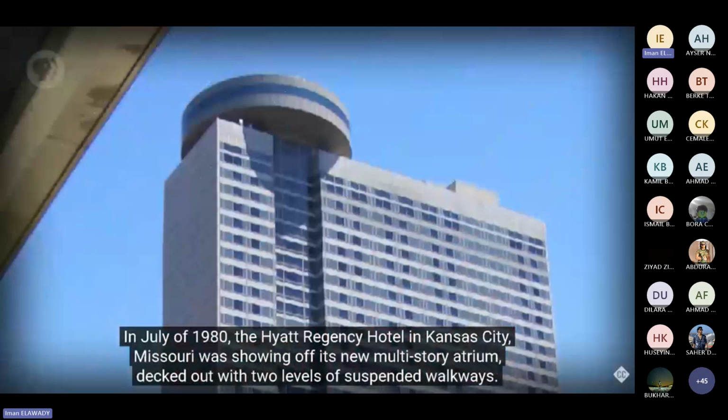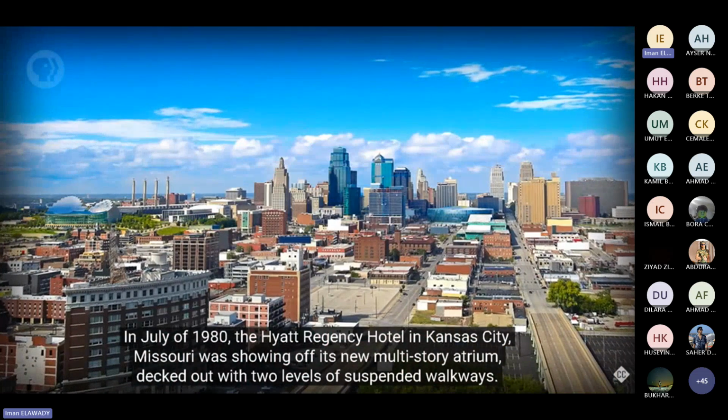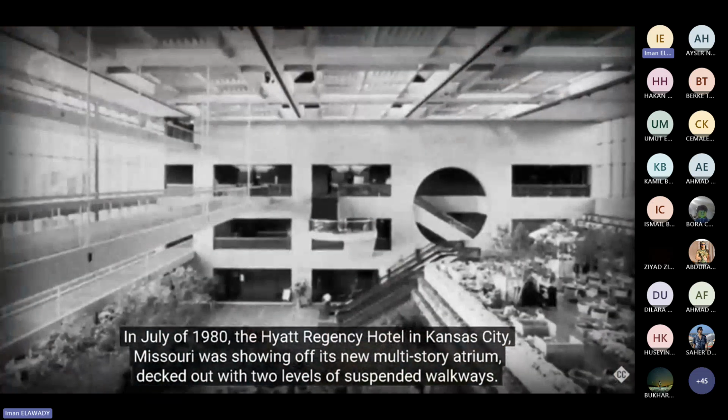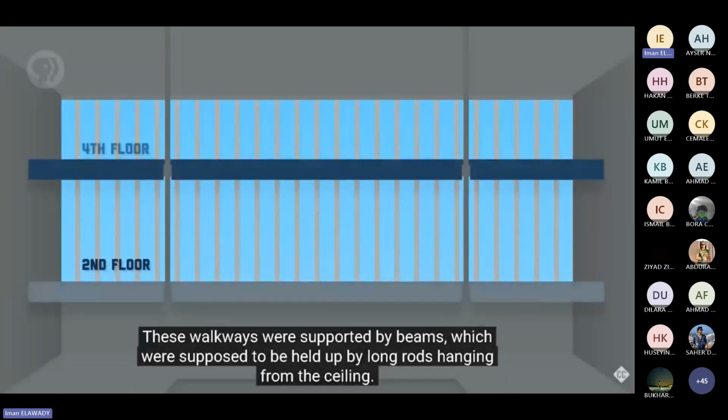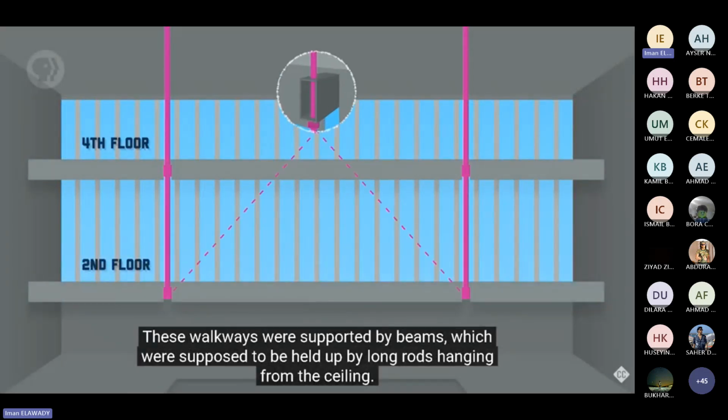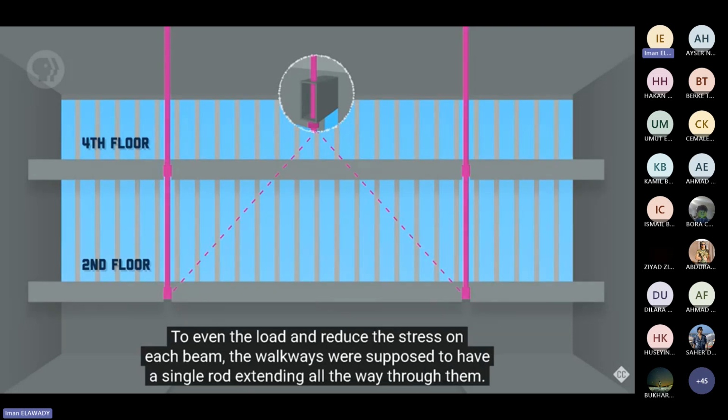In July of 1980, the Hyatt Regency Hotel in Kansas City, Missouri, was showing off its new multi-story atrium, decked out with 2 levels of suspended walkways. These walkways were supported by beams which were supposed to be held up by long rods hanging from the ceiling. To even the load and reduce the stress on each beam, the walkways were supposed to have a single rod extending all the way through them.